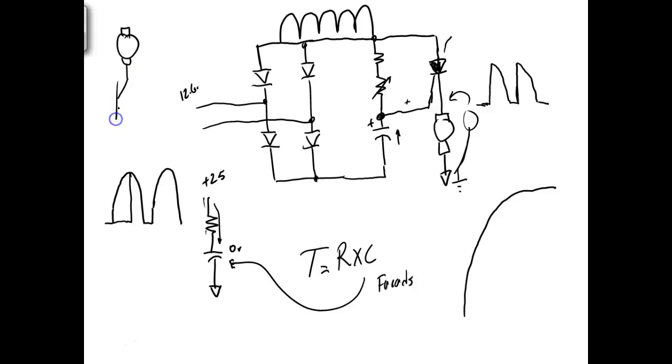So I could come up here and use a transistor. Now what's the problem with a transistor? Well, if I have 25 volts right here, and I want this motor to run at a certain speed, let's say I want it to run at 3 volts, then my transistor is going to have to drop 22 volts. And if I push current through a voltage, what does it create? If I push current through a voltage. Yeah, you're exactly right. Creates that right there, right?